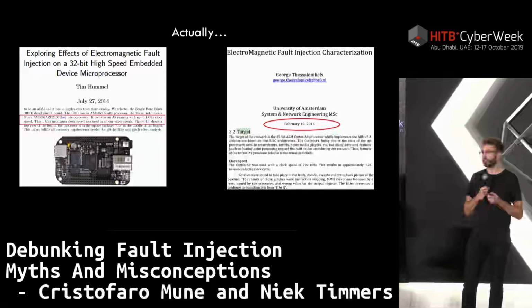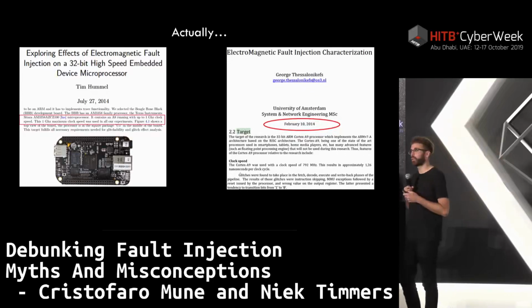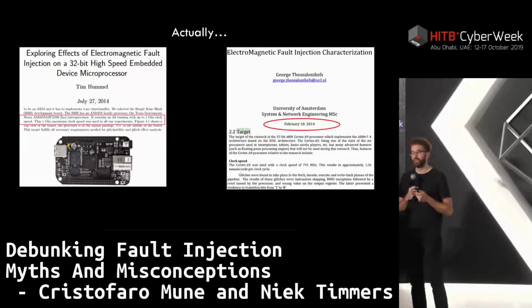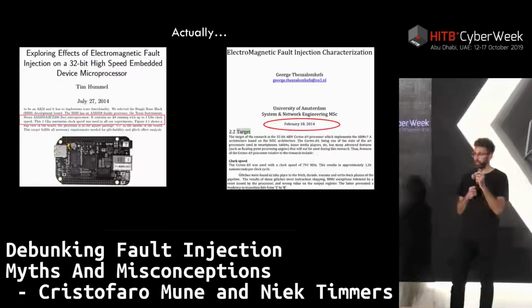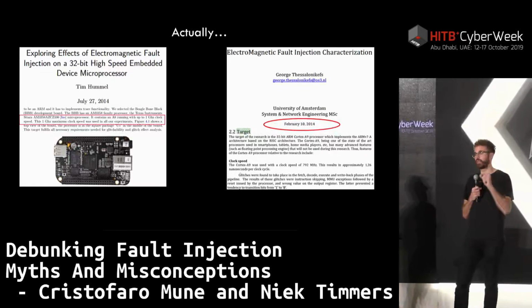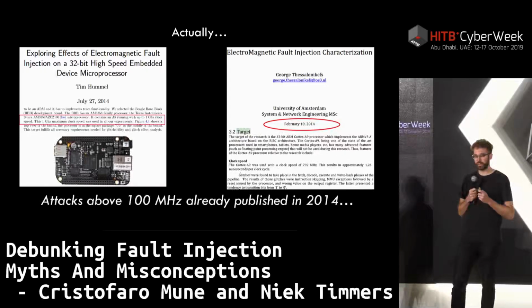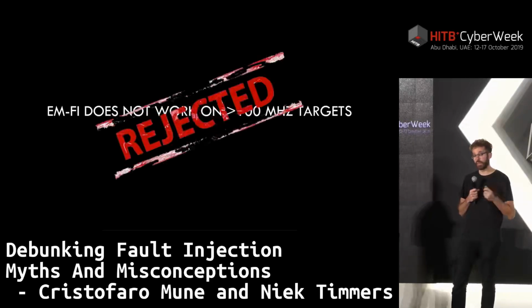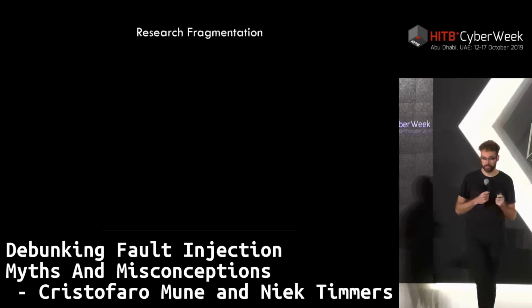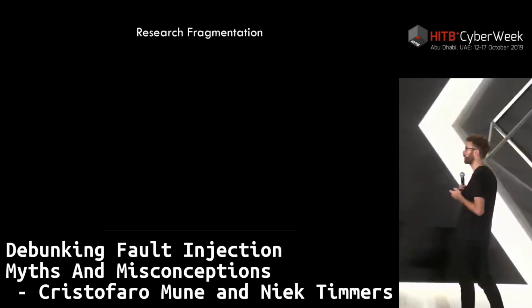Another person in 2014 did exactly the same on a chip running at a slightly slower speed, but still 800 megahertz, in order to take control of a device, modifying instructions at the granularity of one instruction using EMFI. I would like to debunk the myth, but I would also like to stress that there's some fragmentation in the research being done.